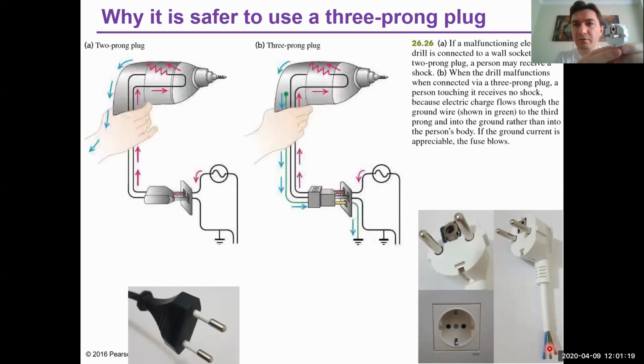So what you see here is that there is a metal here, and there is another metal here, and in UPS outlets you have to use this one. This is also connected to the ground, so they go to that line here. This double color, green and yellow, shows us the ground line. This is the phase line or hot line. This is the neutral line.